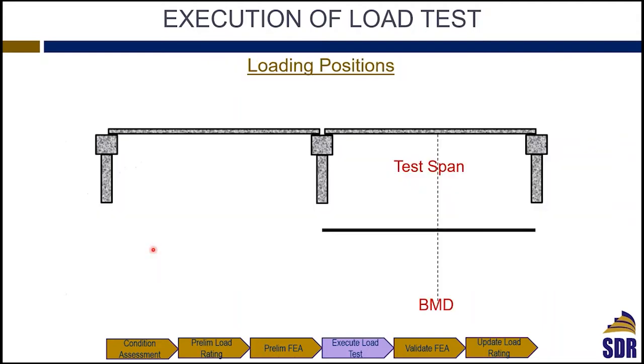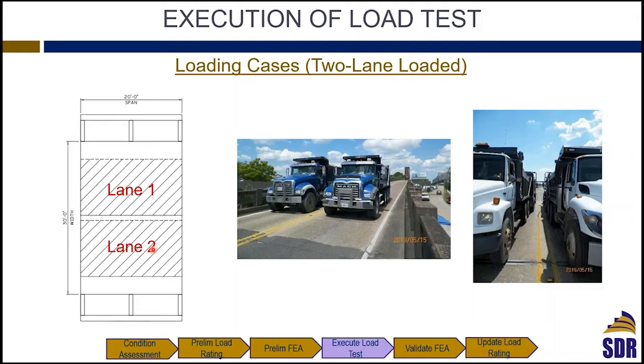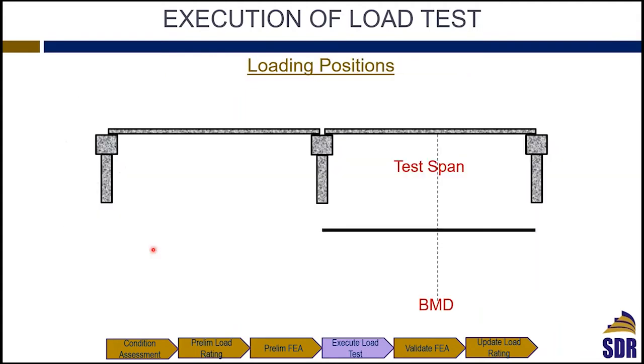After we do the field test, now for the load, do we go in the field and apply the maximum load on the span? So taking this as an example, this is a simple span, slab span, and typically slab spans are governed by their flexure strength. So we're looking at the mid-span moment for this simply supported slab. So do we go and apply the maximum load on this span to produce the maximum moment at mid-span? I don't think that's wise.